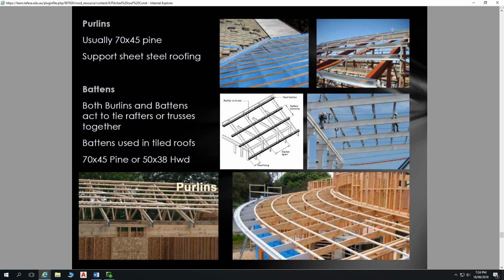Even though we know that structurally, in a strength fashion, when you increase the depth of a member, it increases its spanning capability, its strength. The timber framing code span tables typically treat purlins and battens the same. Not exclusively, but typically. So often it's far simpler to design and specify battens for sheet roof as opposed to purlins.